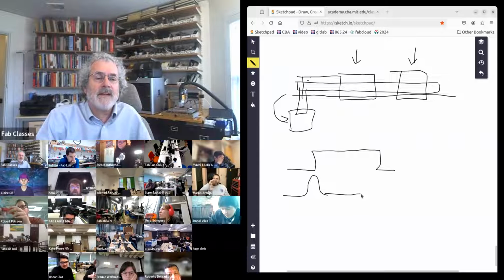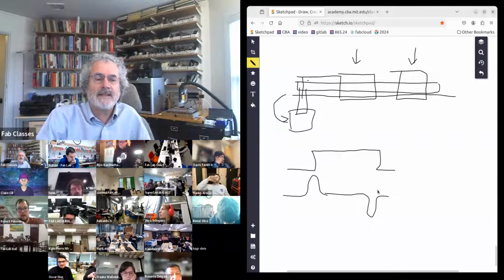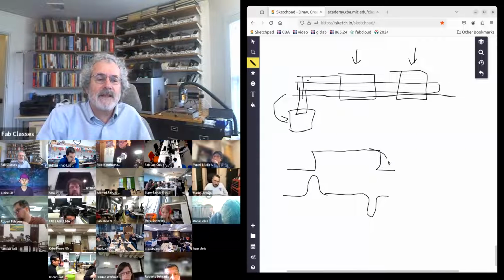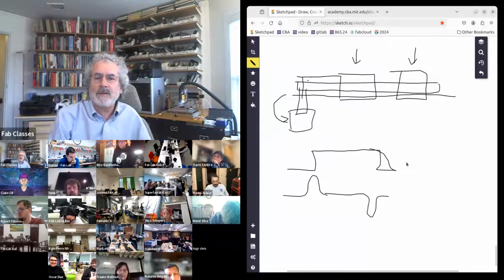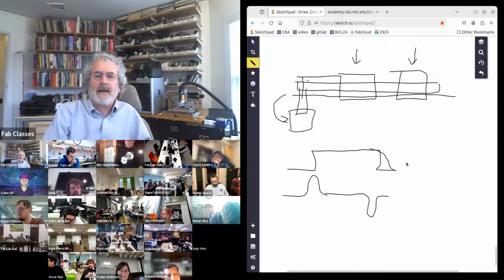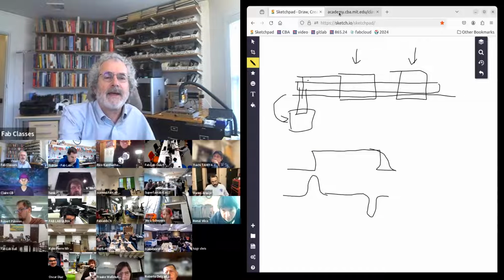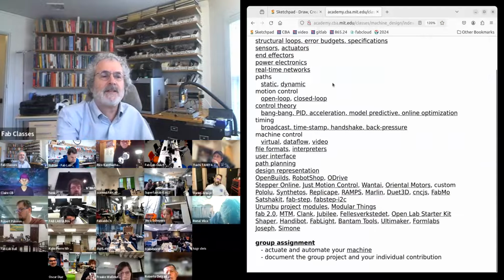When you get to the stop, there's a big deceleration. The whole machine jerks again. And there's no reason for it to stop perfectly where you want. It's likely to keep going and miss a little bit. So you slam it, you slam it back, and there's vibration and it's poor control. That's called bang bang control.